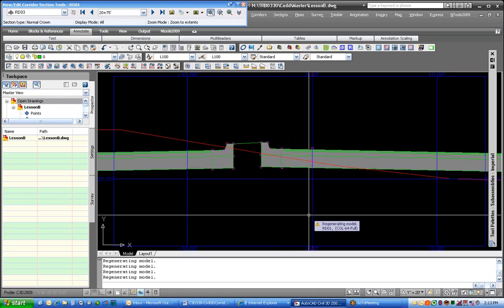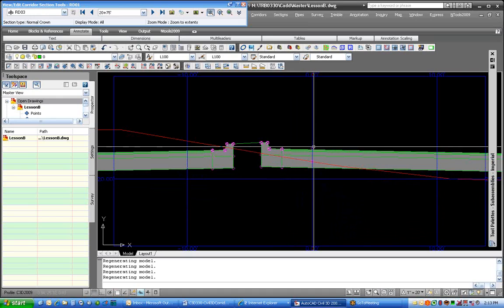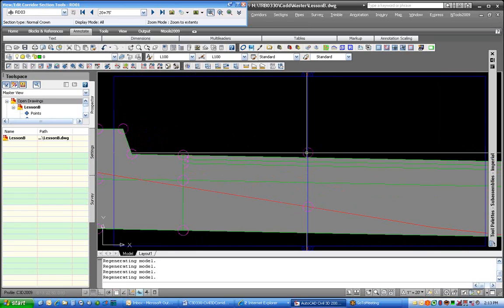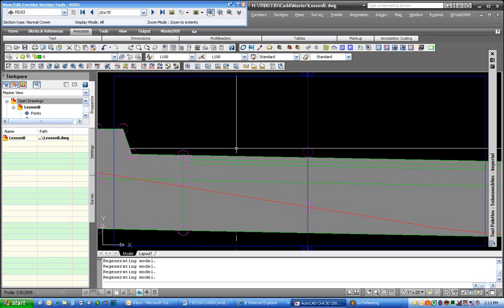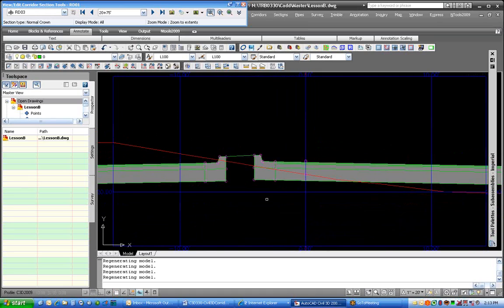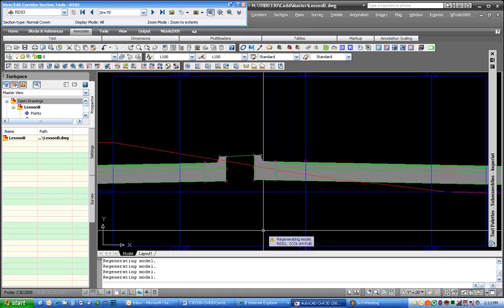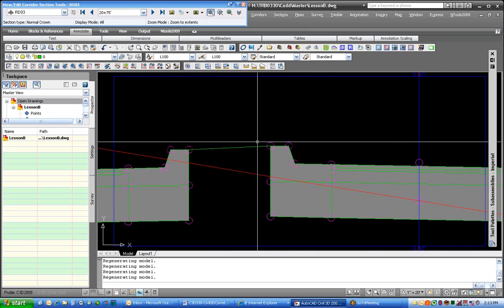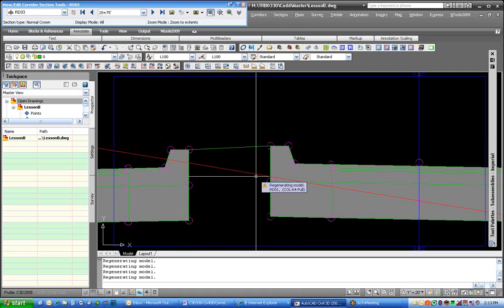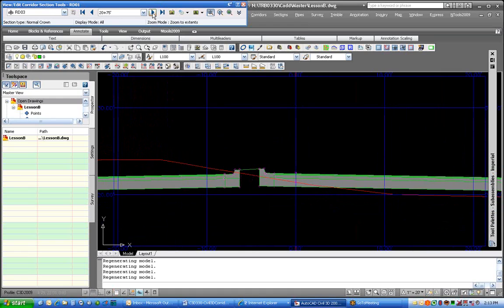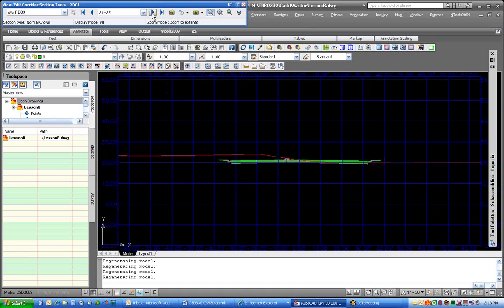The flaw I see with it right now is it's still holding. There's our, this circle here is our centerline crown point. It's still holding that 2% down off of there, so we may not have quite the correct cross slope on there. Somehow I need to change it so it goes up. So I may have to do a profile for the edge of pavement to get it to follow along with that. But you'll see this link transition across here is closing that gap real nice, so we're getting a real nice clean model of how that edge of pavement's going to behave.